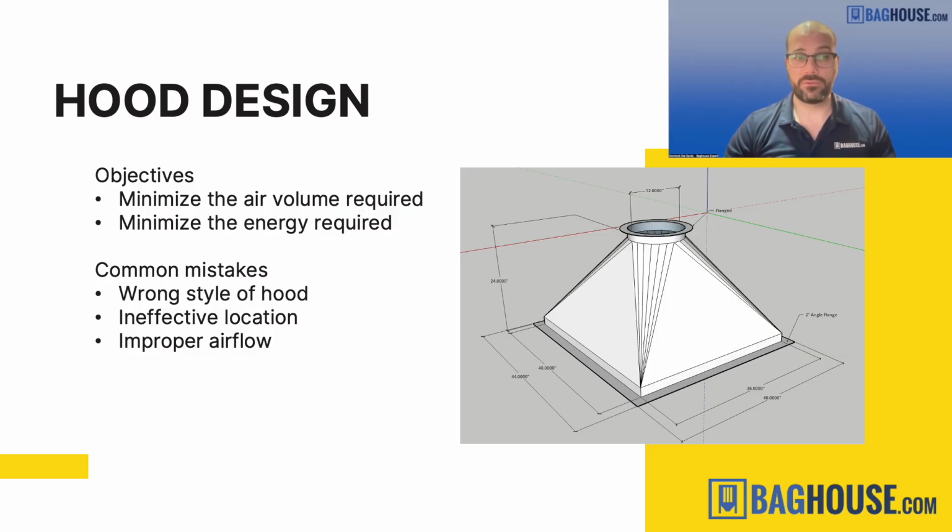Now, with woodworking, what's really useful is that most, if not almost all, of the machines that you will be using, the people who make those sanders, planers, CNC machines, chop saws, whatever equipment you have, are almost always going to do the ventilation or hood design in the machine before you buy it. So when you buy your sander, when you buy your planer, it's going to pretty much come ready with the dust collection hoods or the ports built into it. So that makes this part much easier.